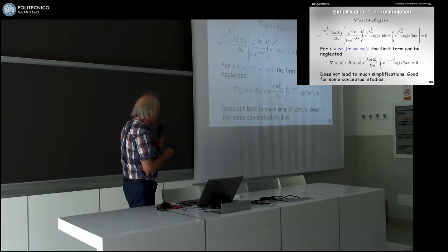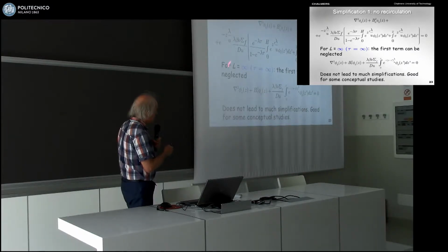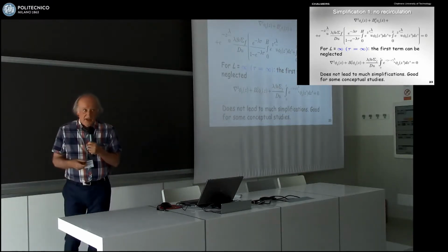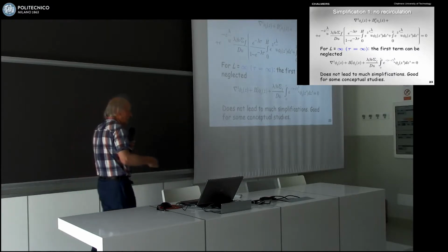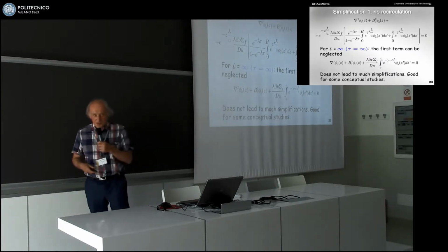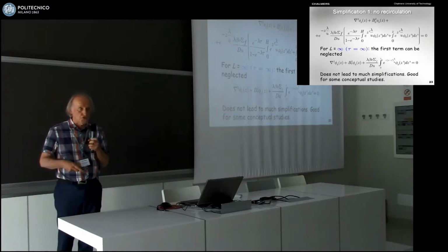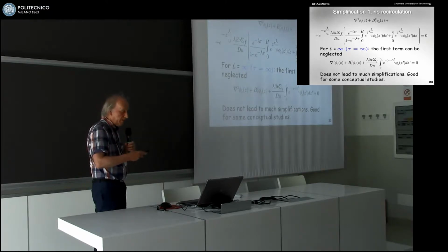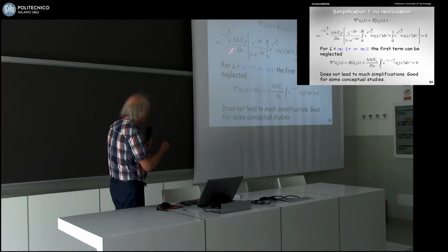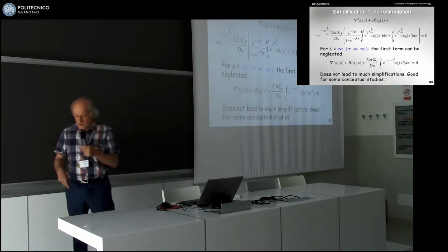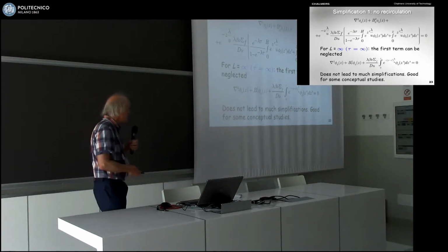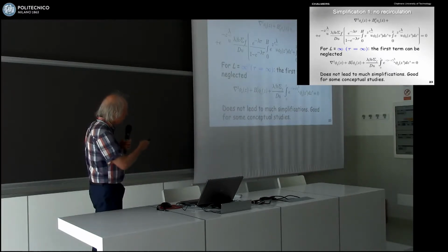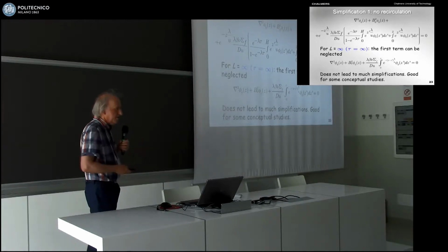So there are two ways of getting rid of either the first term or the second term, by assuming the following. The first one is to assume that the outer loop is so long, or the recirculation velocity is so low in the outer loop, that practically everything decays before coming back. And that means that then we can neglect this term. You can also see it on the equations if you take the limit u equal to 0, and then it will be very easily obtained that the first term can be neglected and the second will be kept.